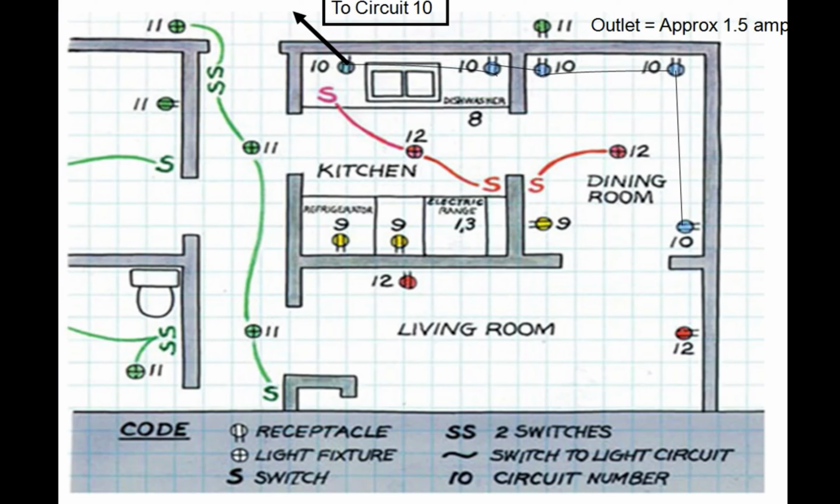So basically, that's how to lay out your panel. You have four circuit breakers, and then if you needed to do work, say on an outlet in the dining room, you would trip breaker number 10 and turn that off so that you could work on them safely.